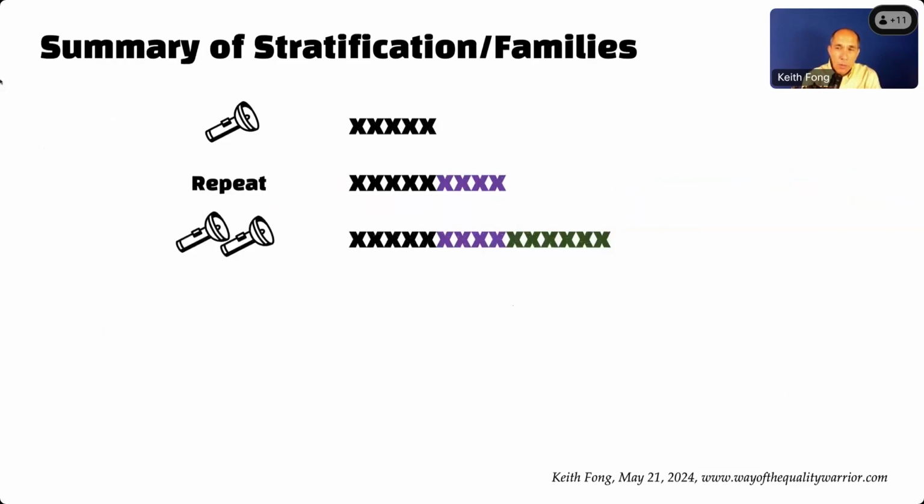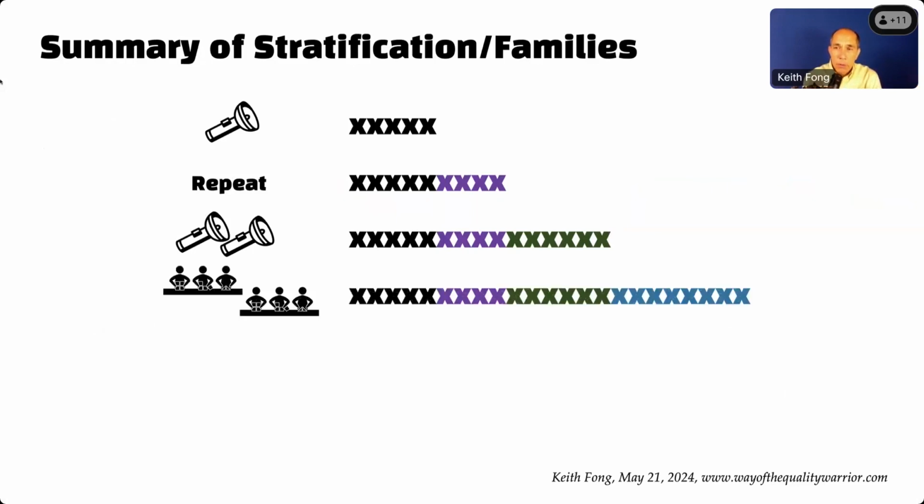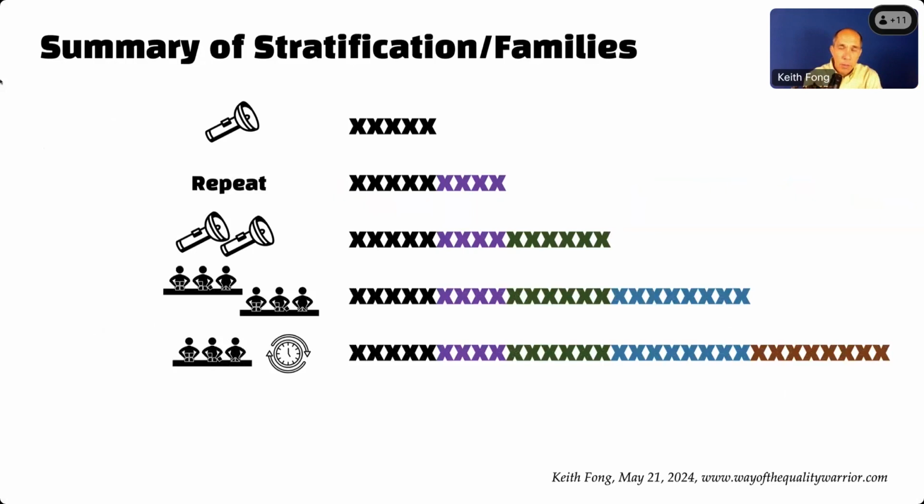And then when we went to flashlight to flashlight, we're bringing in some more potential causes like variation between components, variations in the setup. Then when we talk about two different production lines, we're adding in the production line conditions, the operators, the fixturing, the setups and so forth. And then if we think about the same line but multiple shifts, we're also bringing in a few other X's.